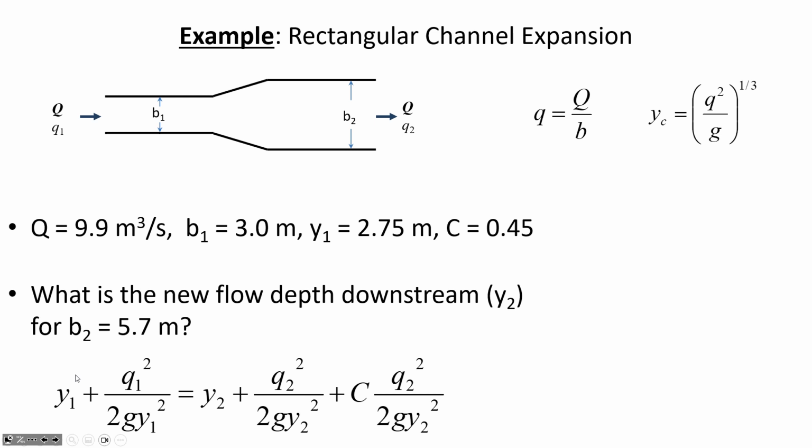So let me just outline what I think the steps are here, and then I'll pause from talking and give you a moment to do the calculations. Find the flow per unit width at 1, find the critical depth, find the flow per unit width at 2, and then into the specific energy equation. So substitute in the specific energy equation, formulate the cubic equation, solve for roots.